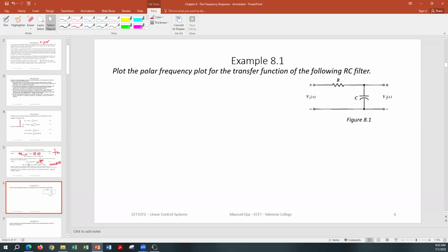So at gigahertz or terahertz, the resistor you use at low frequencies may behave differently, because the effective cross-sectional area becomes smaller. Electrons start passing through the surface instead of being equally distributed over the whole area of the resistor.